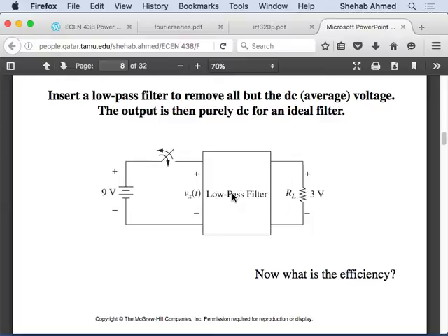If you want to put something in a mobile phone, obviously you cannot pick a big wire. You have to live with a small wire, which means you will have high resistance. So what do you do in that case? You try to reduce the current and maybe increase the voltage as a compromise, because the power loss is I squared R in that resistor. If I increase the voltage and decrease the current, I can transfer the same amount of power with better efficiency, if you want to call it that.